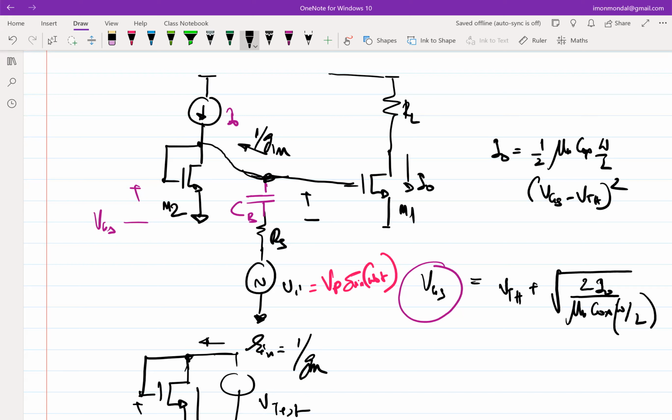Instead of keeping only one single capacitor from M2 to the gate of M1, I'm saying that we can put an R and C in parallel. Where would you want to put them? The same place where you have just now drawn the capacitor. So you want to put a parallel RC between these two? Parallel RC. Okay, so this and this.